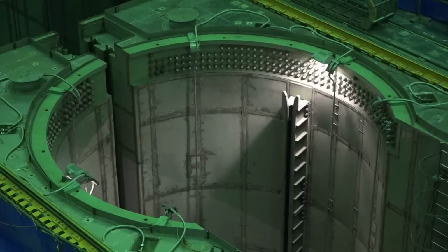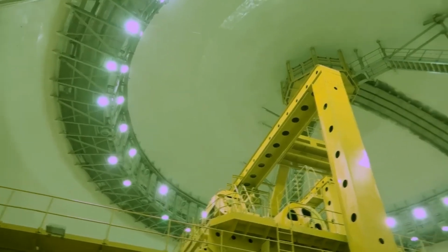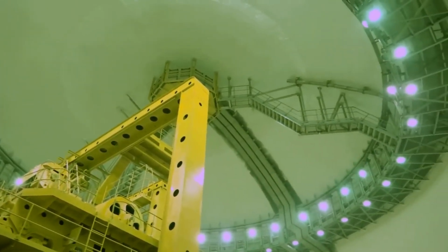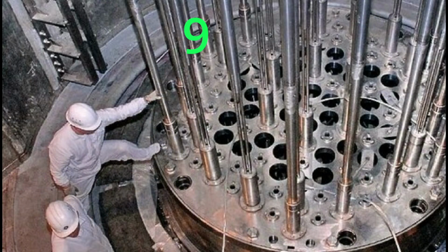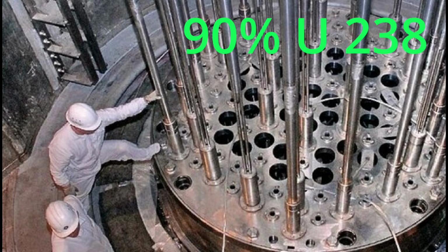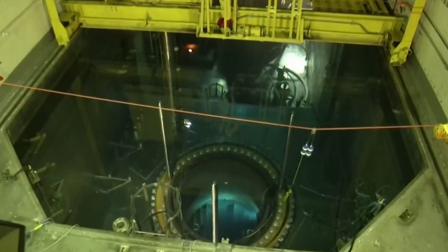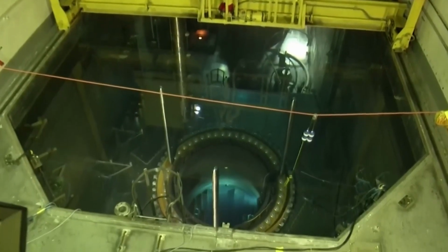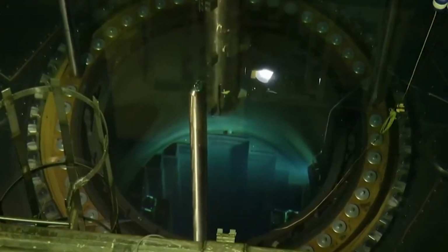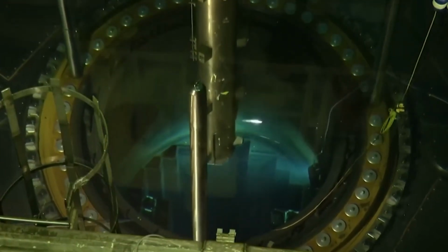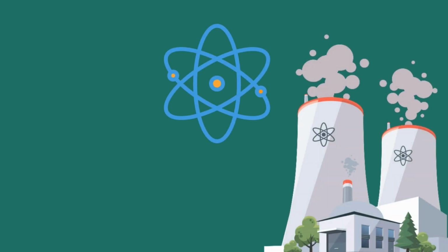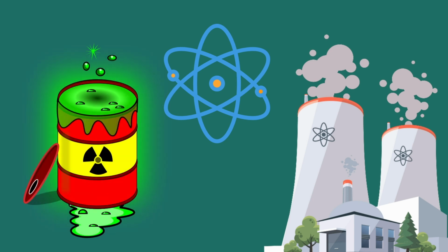The operation of thermal, slow-neutron reactors results in formation of spent nuclear fuel, a cassette with partially burned fuel composition. In this composition, up to 90% refers to atoms of uranium-238, which is unsuitable for use as fuel for thermal, slow-neutron reactors. The spent fuel is withdrawn from the reactor and sent to spent fuel storage pools where it is stored for several years, after which it is removed from the nuclear power plant for disposal or requires special waste burial conditions. Thus, a typical process diagram for nuclear energy generation leads to formation of problematic and environmentally hazardous waste.